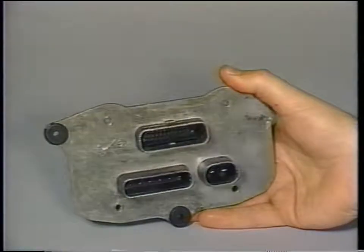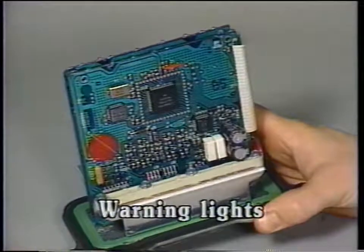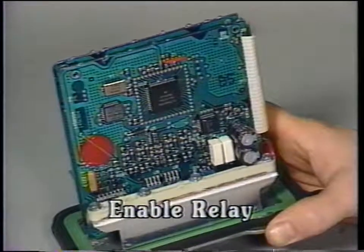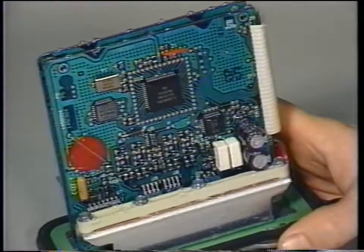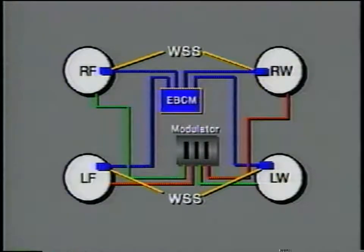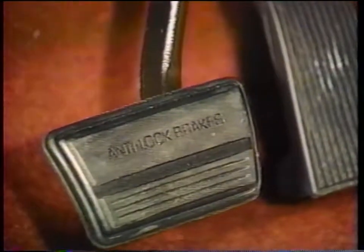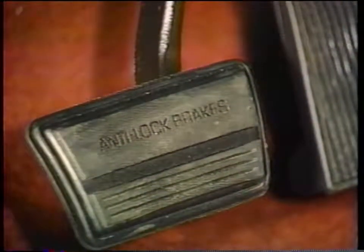Located inside the controller will be a quad driver module. Its purpose is to control the operation of the warning lights and enable relay. It also helps protect the controller against damage in the event of accidental probing. The controller monitors wheel speed through the 4 wheel speed sensors during braking and modulates braking action as needed to prevent wheel lockup. A switch on the brake pedal signals the controller when the brakes are being applied.